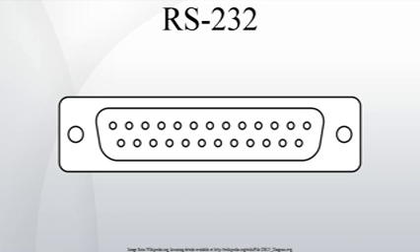Connectors. RS-232 devices may be classified as data terminal equipment, DTE, or data communication equipment, DCE. This defines at each device which wires will be sending and receiving each signal. The standard recommended but did not make mandatory the D-sub-miniature 25-pin connector. In general and according to the standard, terminals and computers have male connectors with DTE pin functions, and modems have female connectors with DCE pin functions.